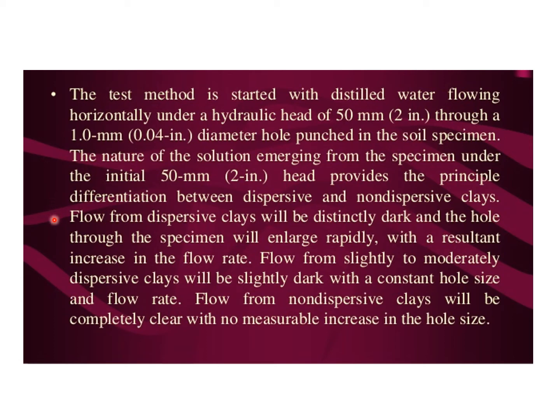Flow from dispersive clays will be distinctly dark and the hole through the specimen will enlarge rapidly with a resultant increase in the flow rate. Flow from slightly to moderate dispersive clays will be slightly dark with a constant hole size and flow rate. Flow from non-dispersive clays will be completely clear with no measurable increase in the hole size.